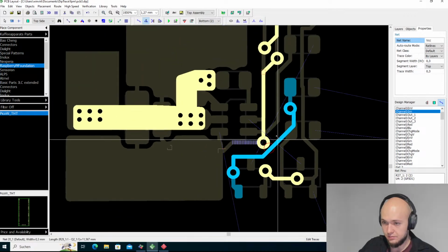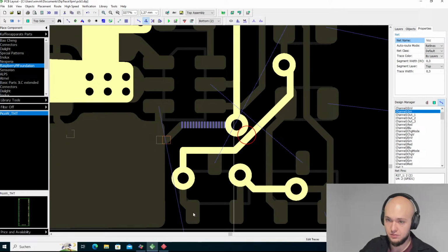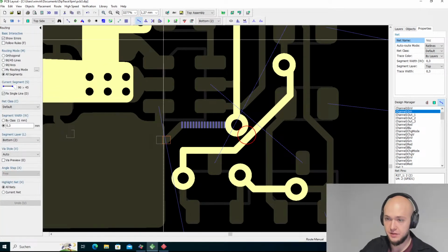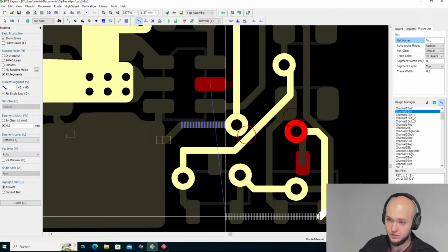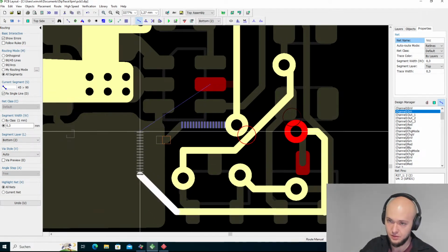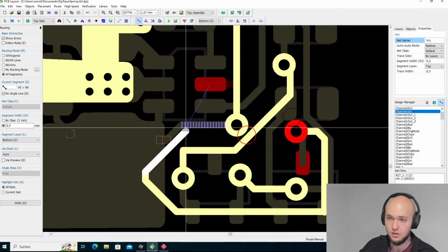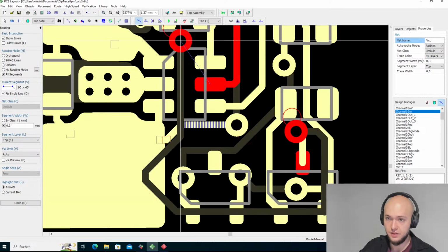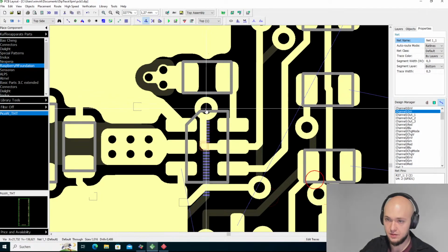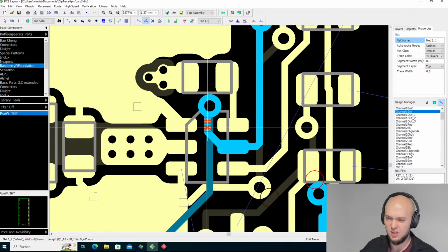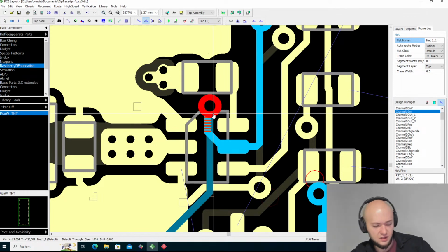Okay, now it gets interesting. Maybe we simply say we do a shortcut. Oh yeah, that's a way better idea. Do it like this and this and this, and move it from the side up, under here, because this trace shouldn't be that. Although it's a really high impedance track, there's 3 megaohms up there. Not a good idea.